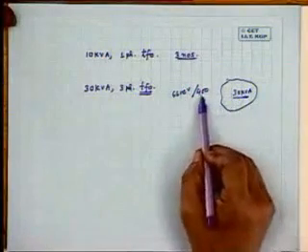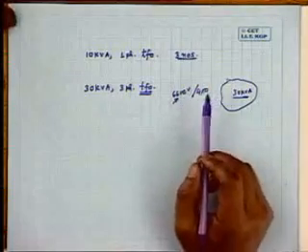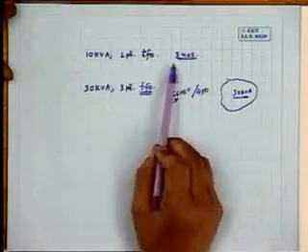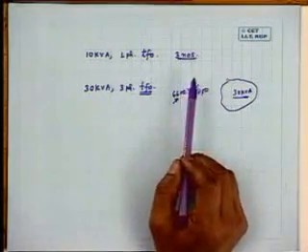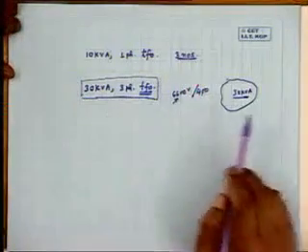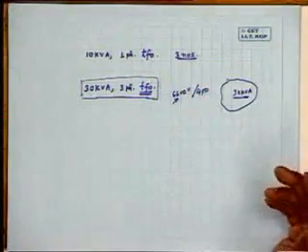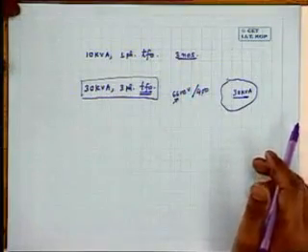Then this 30 kVA can be supplied at 400 volt level when the input voltage is 6600, either by using three single-phase transformers, each operating at 10 kVA, or you can buy a single unit of three-phase transformer of 30 kVA rating. Is it not? Now, which one you will prefer?